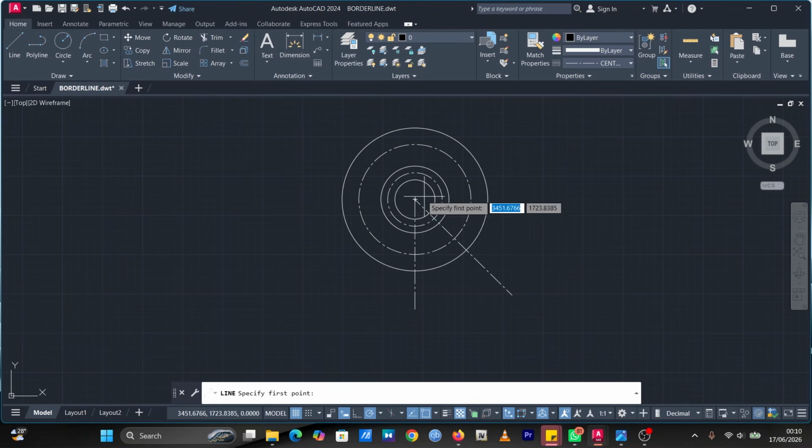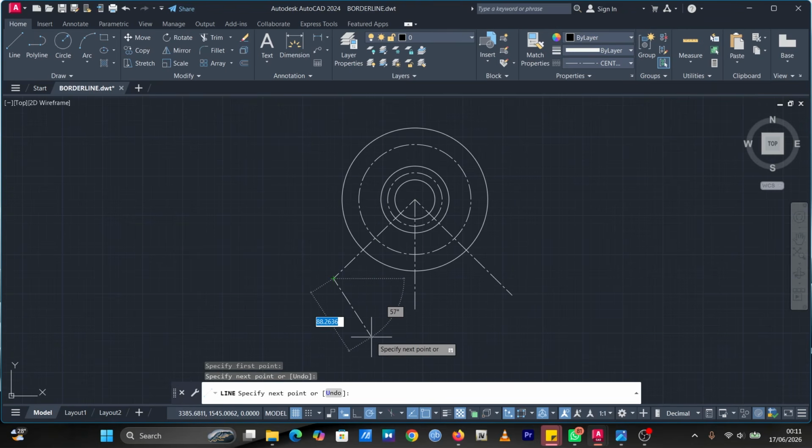You select your line again, you click center, you make sure you get an angle of 45. So 90 plus 45 is going to give us 135. So make sure on the left side the angle is 135, and on the right side the angle is 45. So we have something like this over here. You have these broken lines, something like this over here.